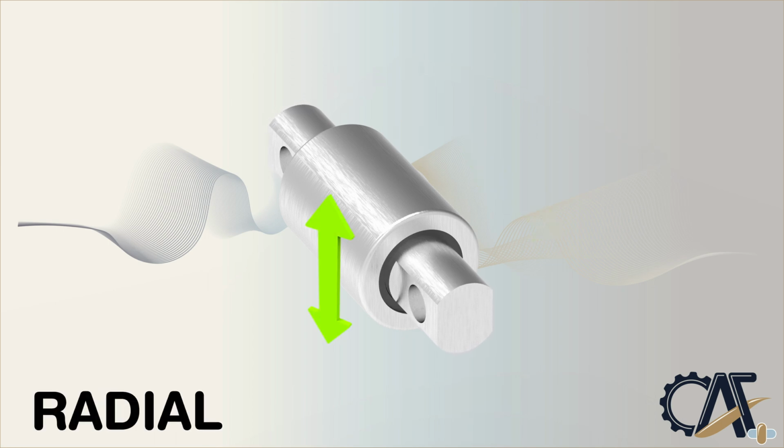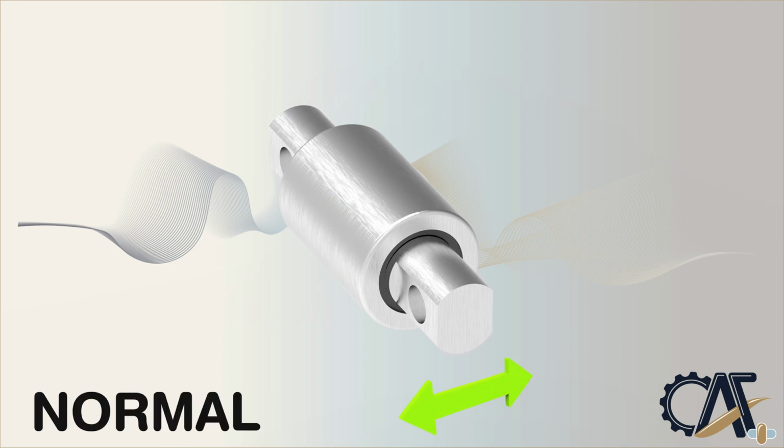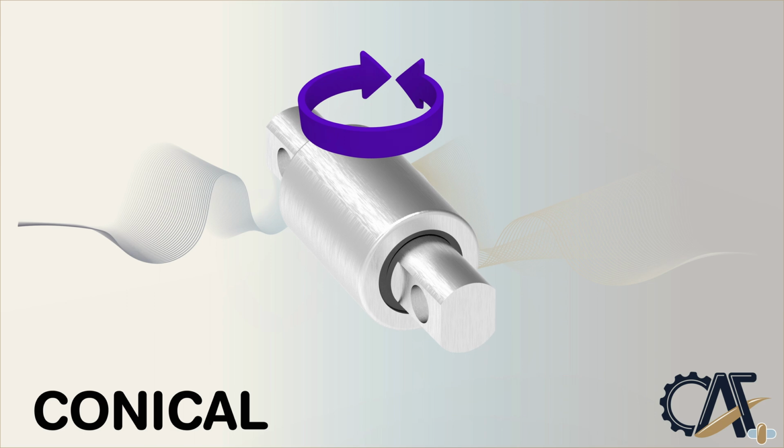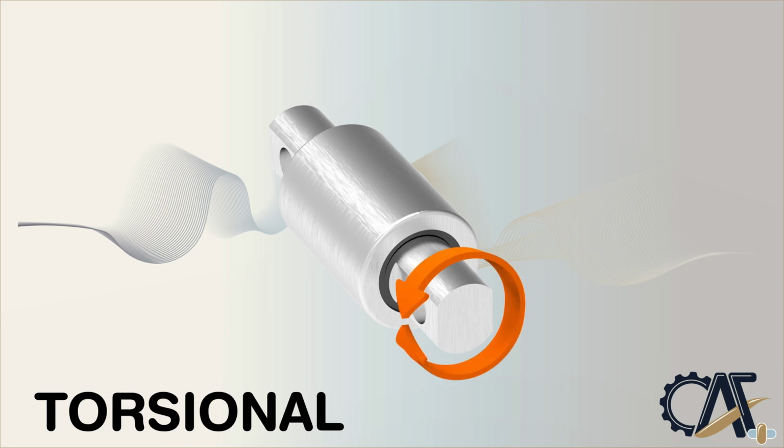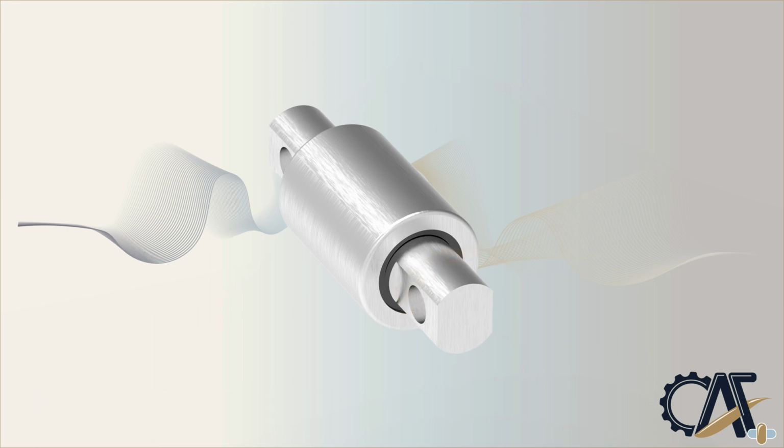One important point about cylindrical rubber bushings is that they transmit significant loads mainly in their 2 principal, radial and axial, directions. In the radial direction, bushings demonstrate high, nonlinear stiffness owing to combined shear, compression, and extension of rubber. In the axial direction, bushings show lower, linear stiffness, as in this case only shear deformation is present. In all 3 rotational deformation modes, torsional and conical, bushings are much more compliant as the rubber is less under stress than the axial and radial deformation modes. In these modes, the bushing acts primarily as a kinematic joint, hence, transmitting a smaller amount of loads.